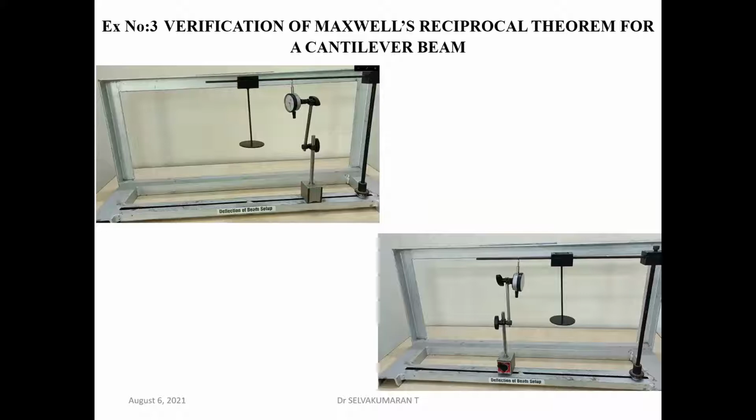So this cantilever beam is made of mild steel, having Young's modulus 200 gigapascal, and the cross-sectional dimensions are width 16 millimeter and thickness, or the depth, 6 millimeter. Let us choose any 2 points randomly on the given cantilever beam. Let us take these as point 1 and point 2. In the same location, the bottom figure also shows point 1 and point 2.